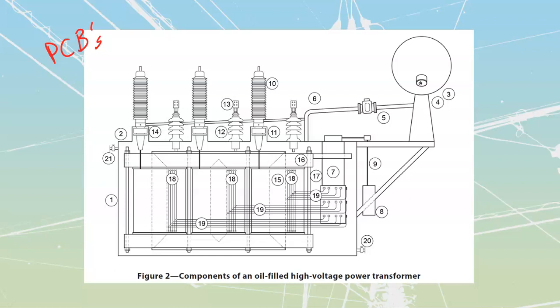As far as our transformer diagram is concerned, it is going to show a couple of main things. You can see the tank and the lid, and the conservator tank, which is where we're going to hold a bunch of our stuff. They've got the Buchholz relay, which is basically going to be something over here that is going to detect gas bubbles. Anytime there's a bubble that goes through here, it is able to send us an alarm signal, because gas bubbles would mean that we have usually got arcing inside of there.